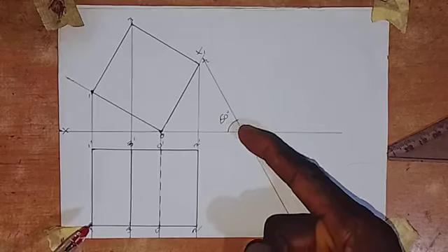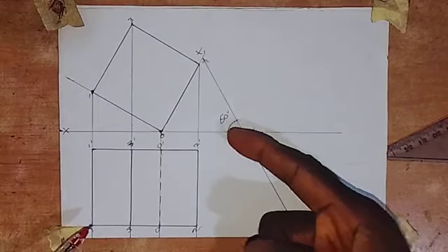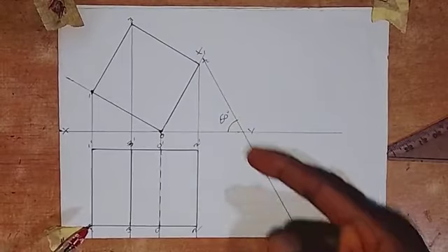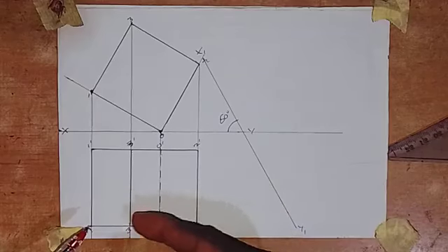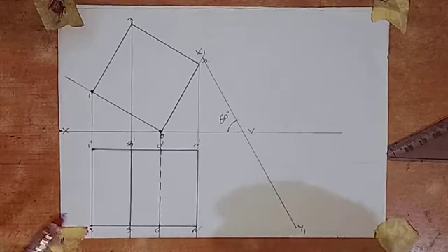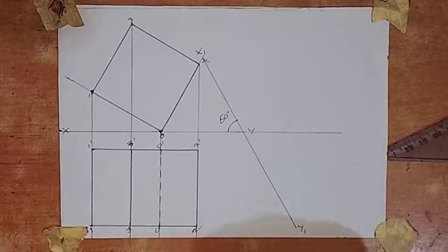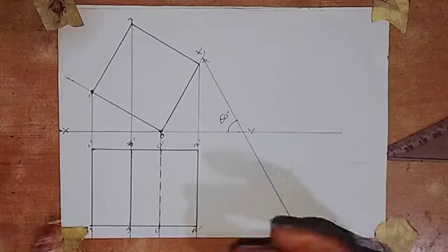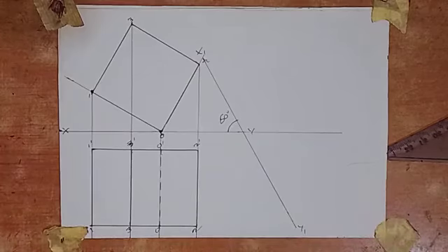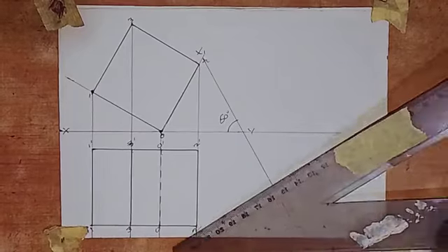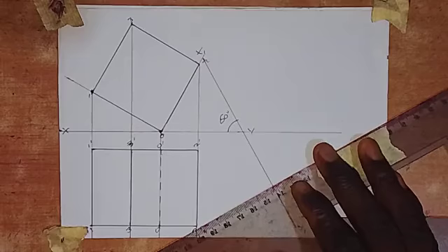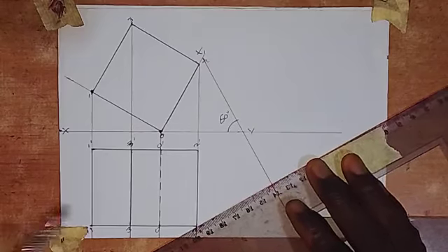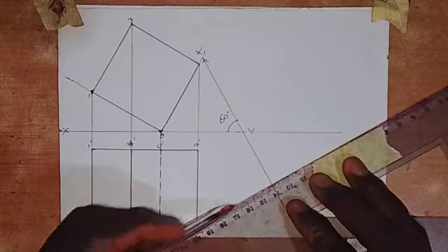So if the angle at which the ground line is to the XY line is 60 degree, and we are to draw a line that will be at a right angle to this line from each of these points, it means that we have to look for an angle that will make it 90. Okay, so 30 plus 60 will give us 90. So we have to use the 30 degree side of the set square to produce the line. So we come to this point here, the 30 degree side of the set square. So we draw a line in this direction.